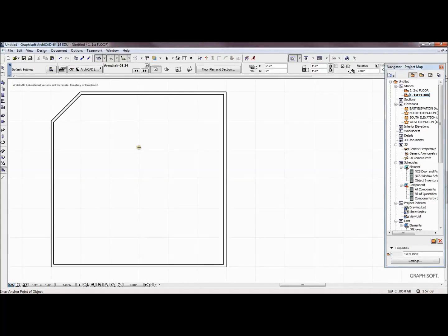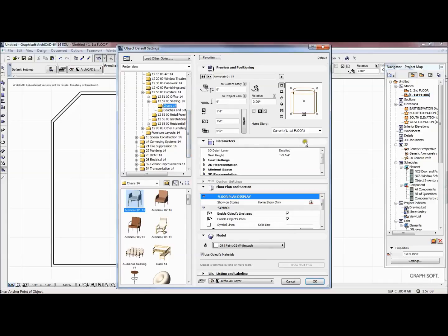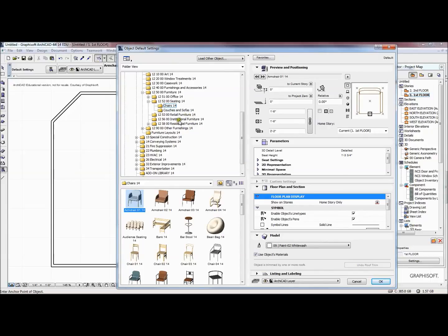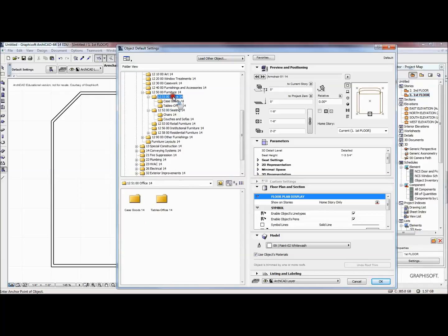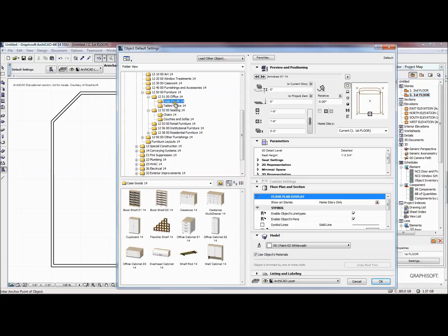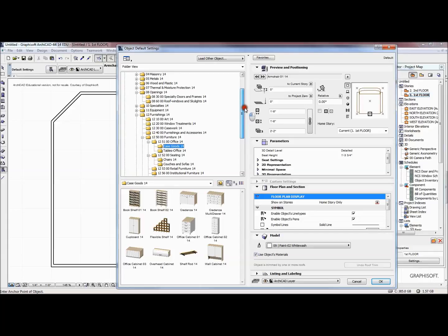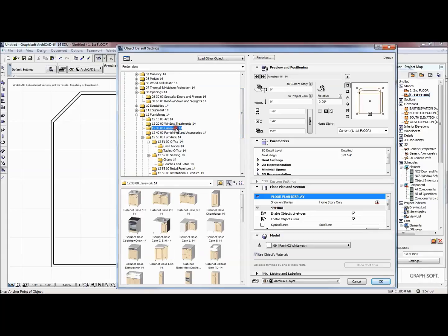Okay, so now let's say that we have our basic wall perimeters and we want to begin to drop different objects in. If I hover over the object menu over here on the left hand side and I double click it, I will get a whole sequence of menus that are here, and these are the different objects. Right now it's hovering on chairs, and you can click on all of these different items that you can add to a house with all different kinds of functionality. One of the ones that I want to go to is called casework, and that's where the cabinets are. The cabinets are in casework, and so let me work with a base cabinet here with a corner sink.